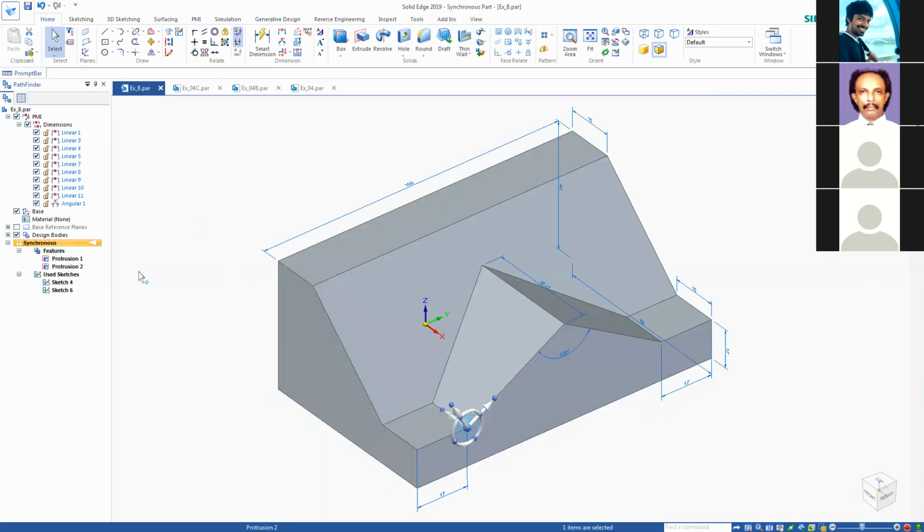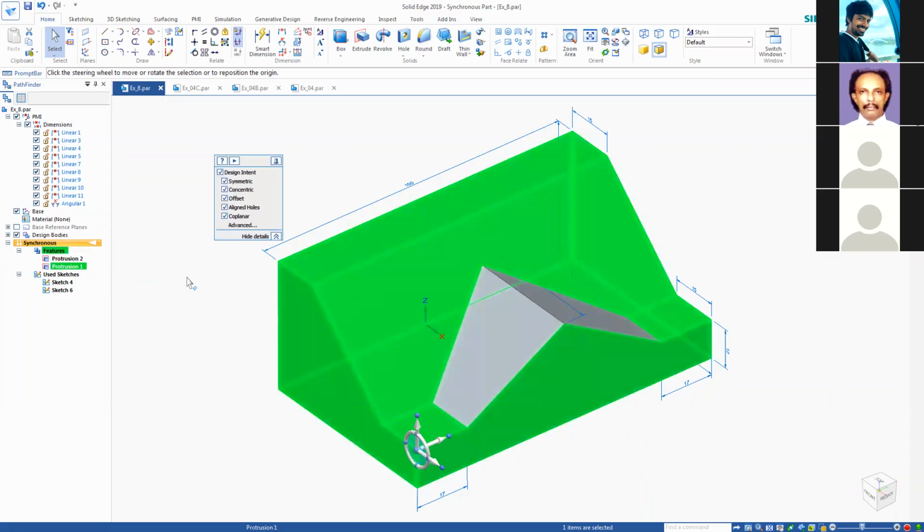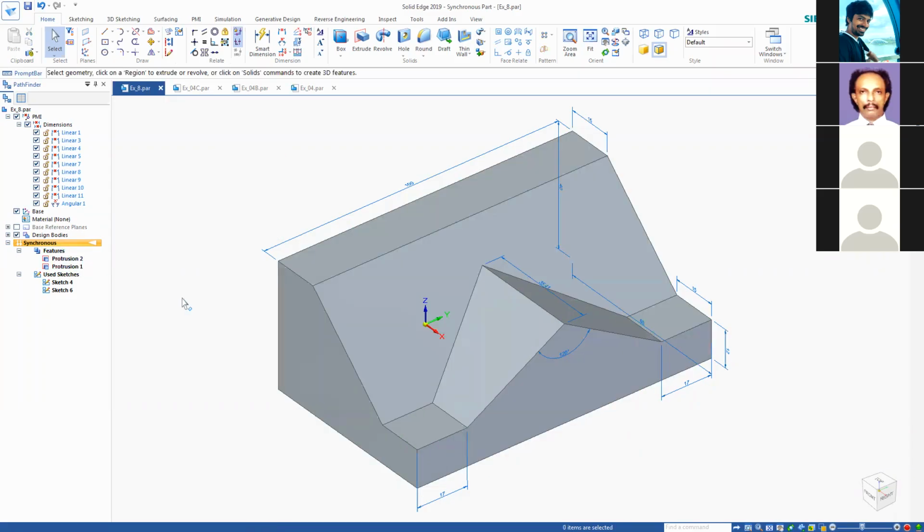Now remember, in ordered modeling, you cannot change this order. You can do this one as long as there is no relationship. What sort of a relationship? We call the parent-child relationships. But here, if say this is the second part, let me take it above the first part. You see now? That appears first. The other one is next, which is completely different when you compare it with the ordered modeling.